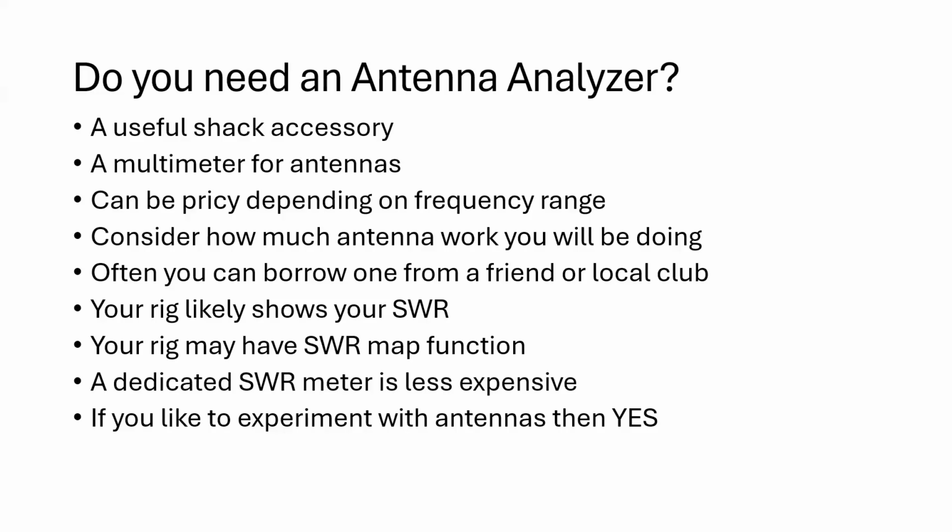So, yes, your rig shows SWR. Some rigs, I'm calling it an SWR map function, like the G90, will take a frequency range and check the SWR. That's very handy. You may want a dedicated SWR meter. You could get by with that. All right. But if you like to experiment with antennas, I would say yes, you need an antenna analyzer. And that is the bottom line here.